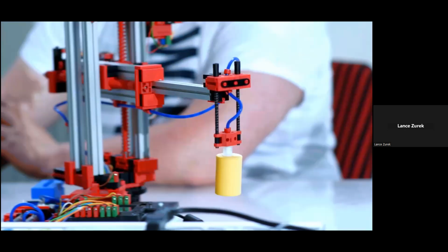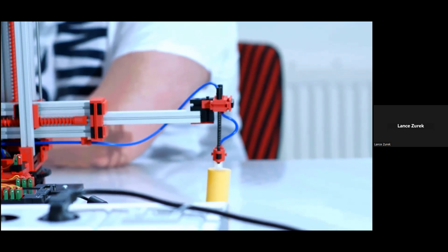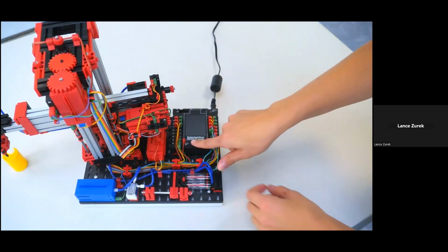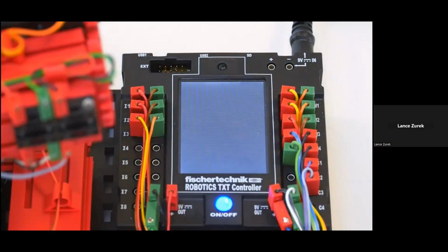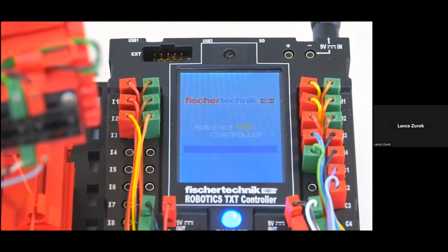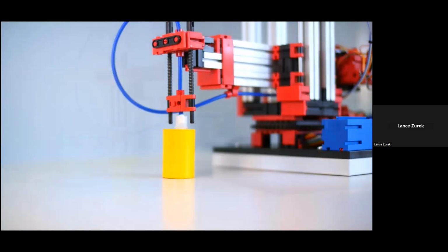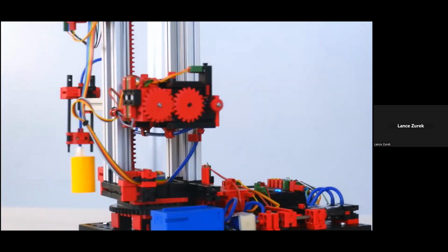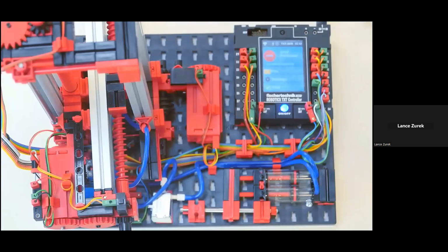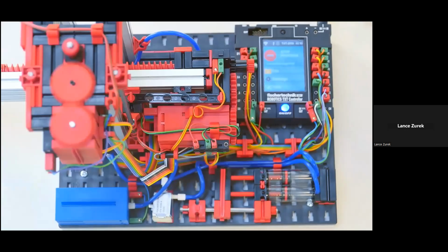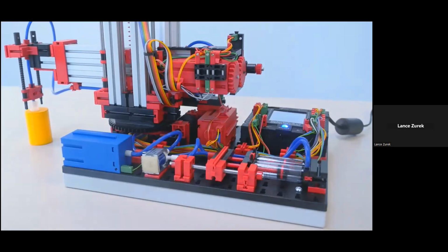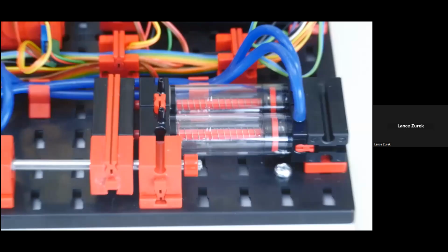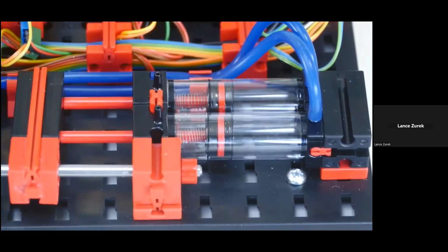The model's dimensions are approximately 9 by 19 by 15 inches, and it has a weight of just about 7 pounds. The 24-volt version of this model, as well as all of the first 5 24-volt models that we're going to be looking at today, each have a relay board for motor polarity reversal and both a multi-pin connector, 34 pins with a grid of 2.54 millimeters, as well as additional PCB terminals with push-in connections for all inputs and outputs. Again, the 24-volt version of this model, as with all of the 24-volt versions, will require the end user to provide the PLC and the program.